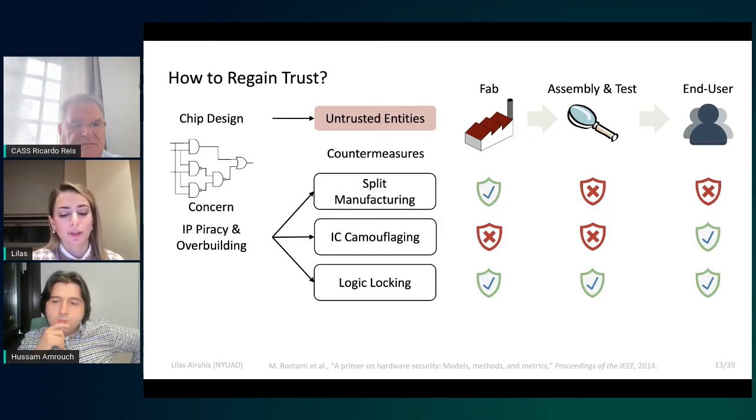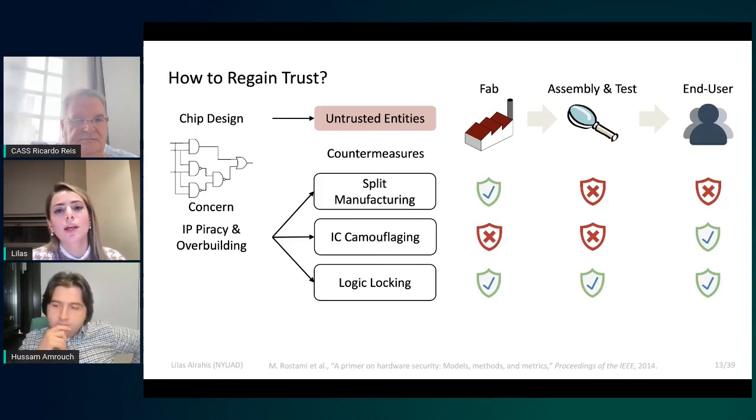The example I showed you earlier, in which we do logic locking and then perform resynthesis to optimize and hide the logic locking, is actually for the benefit. It makes this key logic more difficult to isolate, since it is embedded into the design. And the key logic will not dissolve completely, because it is controlled by primary key inputs. It will be there, and the optimization will further help to embed logic locking into the design.